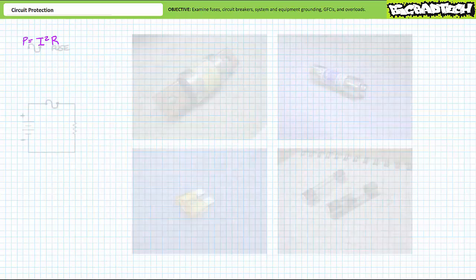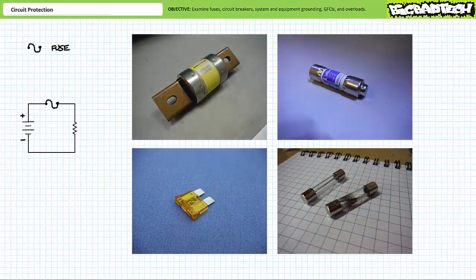This is the most fundamental of series circuit properties, and protection devices make use of this fact to selectively enable or disable current flow. If a protection device is closed, it allows current flow to the load, whereas an open protection device does not. Let's first introduce the fuse. A fuse is a metal alloy element that is purposely designed to melt at a specified rated current and open the circuit and halt current flow. Here's the schematic symbol for a fuse. It is a two-terminal device placed in series or in line with a load that it is intended to protect.